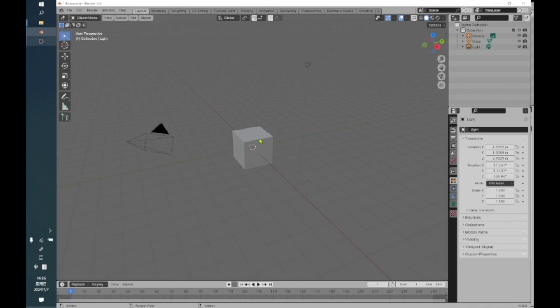But what is important is that, if you have objects, don't think about unifying them too early with the Bool tool. As long as you're not exporting, there is no reason not to keep them as objects. Sometimes it's necessary to do them as one object, sometimes it makes sense, sometimes it doesn't matter.